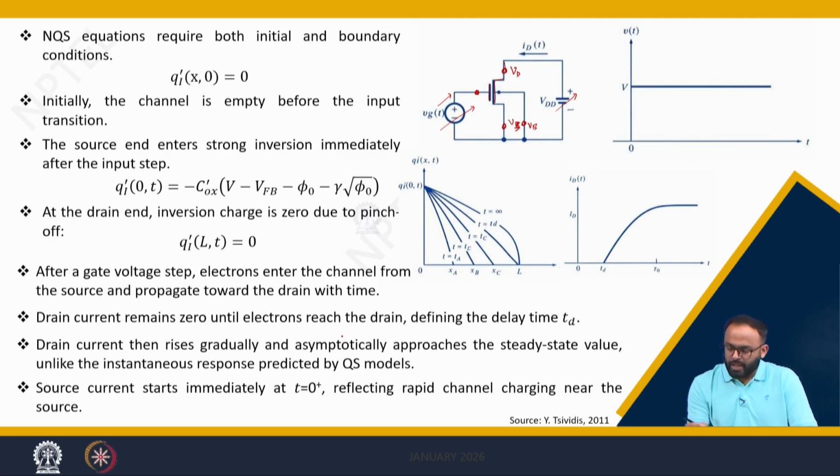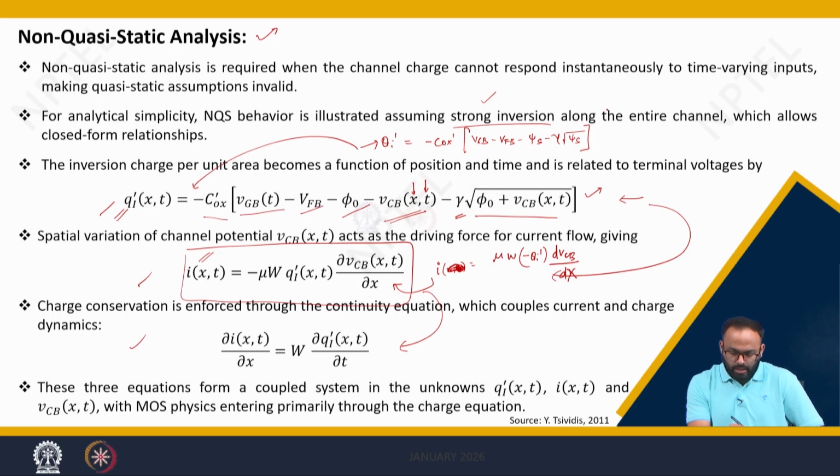Only VG is varying, and we will see what will happen if VG varies abruptly. In the previous lecture we saw what will happen if V is varied as a ramp function, a slowly varying function. However, here the voltage we are applying is abruptly changing, right? Because of this abrupt change in the voltage, how will my charge carriers in the channel respond? This can be solved by the previously defined set of equations.